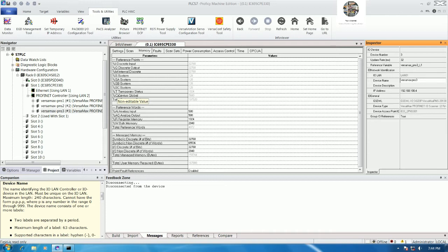We can disconnect the LAN cable from this module and then connect it to our computer back, because we already set the name and IP address. And then let's connect the LAN cable from node number 1 to this module. Okay, I will connect.